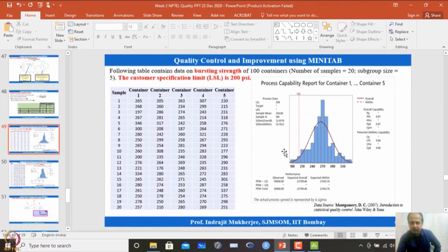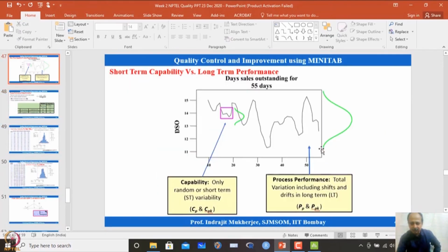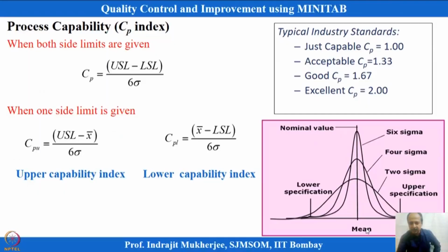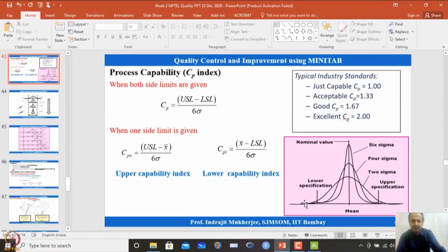CP formulation will be this one, which I am using over here. This is the formulation which uses USL minus LSL, that is the tolerance or delta values over here. That is plus or minus 0.034, that is the total width of that, 2 times of that, and divided by 6 into standard deviation over here. There is a method of calculation of standard deviation, that we have to discuss afterwards.